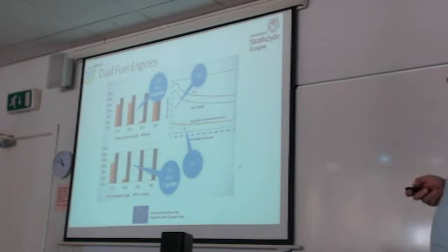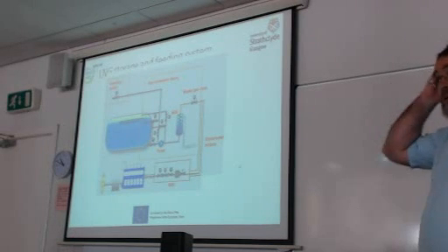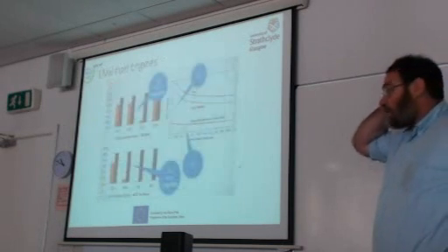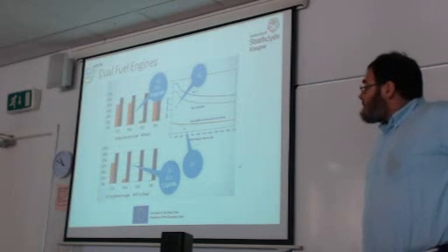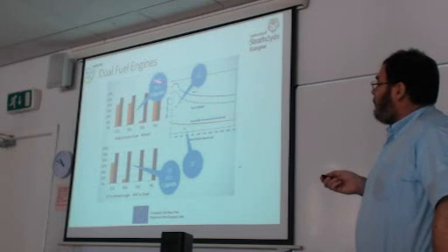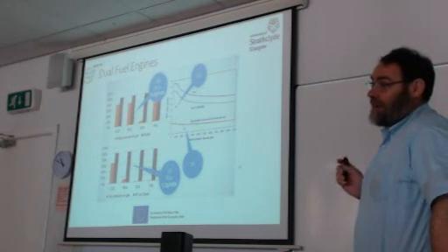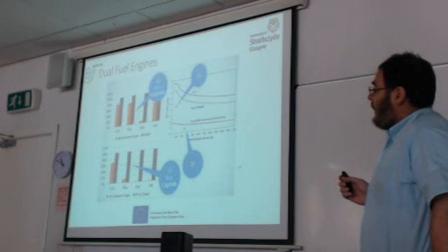Gas dual fuel engines with premixed combustion can comply with Tier 3. In conclusion, additional measures are required in the case of gas diesel engines after some years when the Tier 3 level will come into effect. And as we discussed, there are only two ways: either SCR, EGR, or a combination of these two.